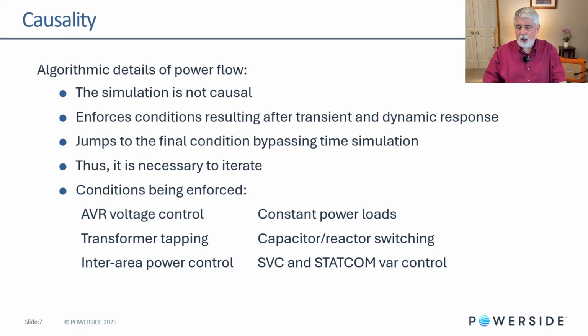SVC and STATCOM VAR control, which has feedback controls built into them, but which maintain criteria within them in which they're going to hold voltage and hold VARs. Often for STATCOMs, there's a volt-VAR curve that's involved there. And there are many more conditions that are actually being enforced in modern day power flow solutions, but I think that's a good start for us to see.